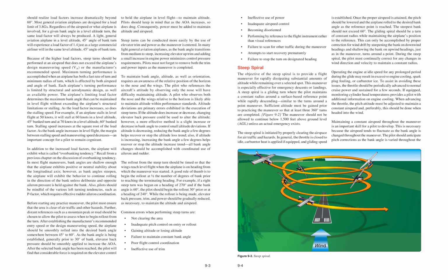Stalling speed increases at the square root of the load factor. As the bank angle increases in level flight, the margin between stalling speed and maneuvering speed decreases, an important concept for a pilot to remain cognizant of.